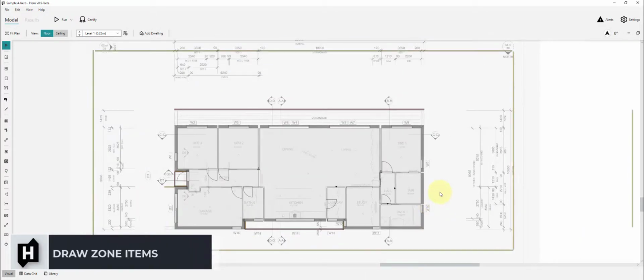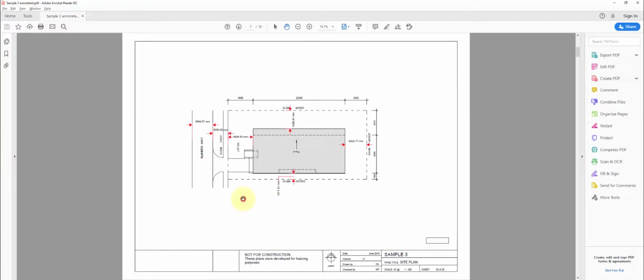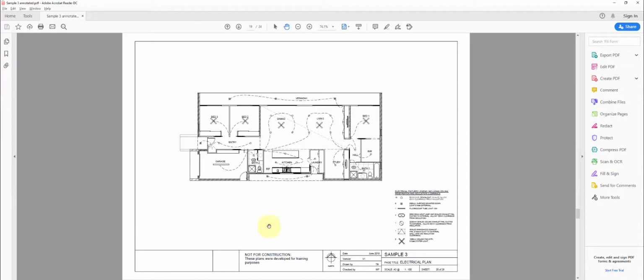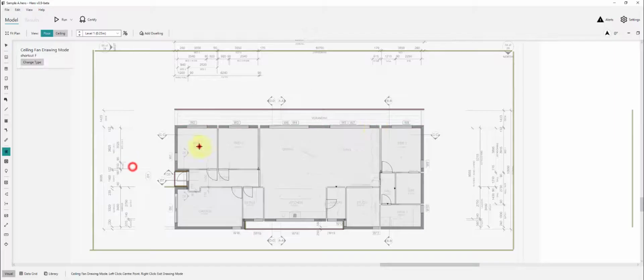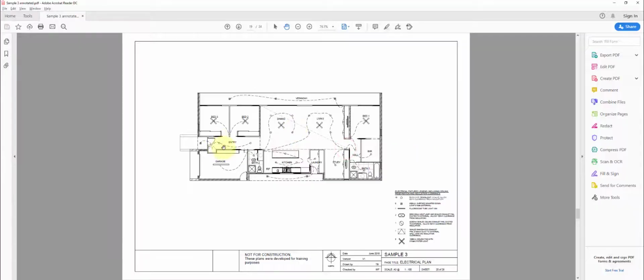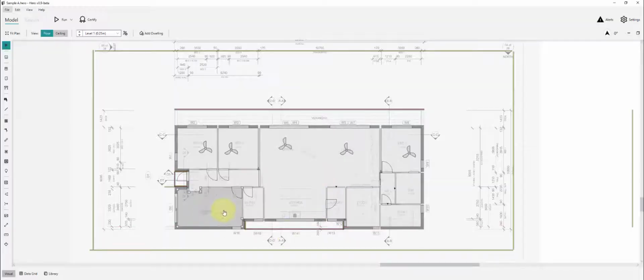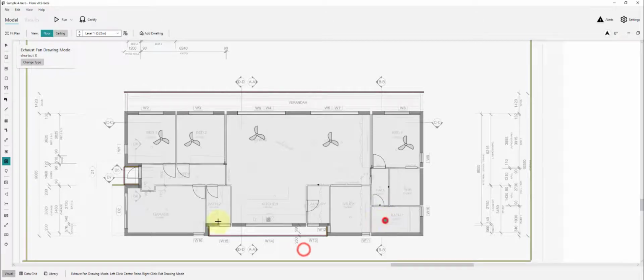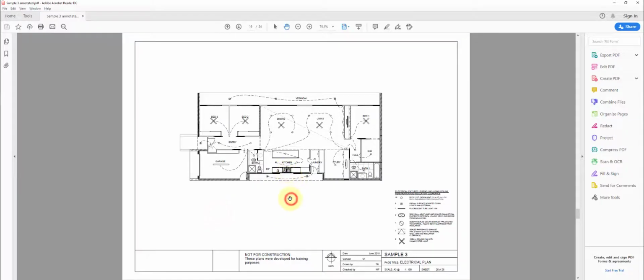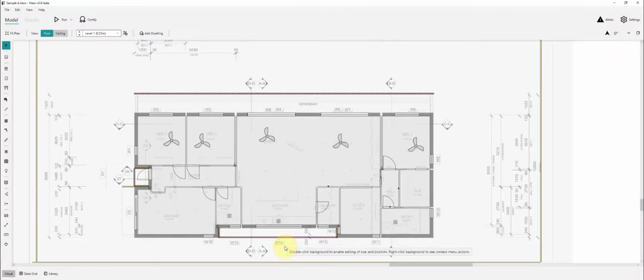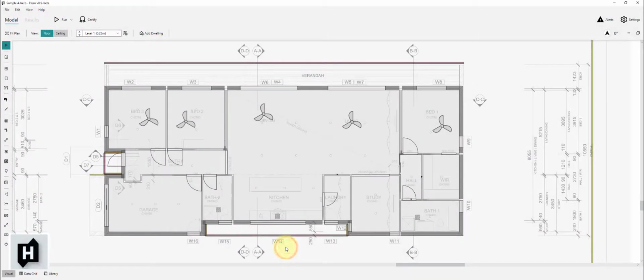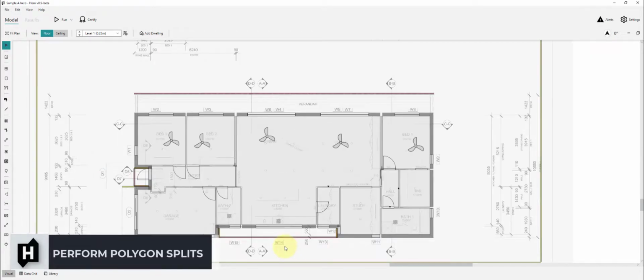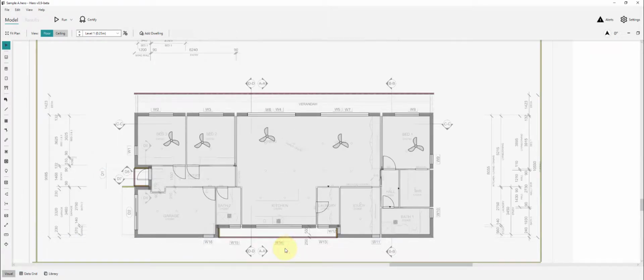Next we generally do penetrations, so let's flick to the electrical plan. Ceiling fans across here. In terms of downlights, we might do this as an example within the data grid, just using the numbers column, as all of the zones have downlight within them. So we'll leave that there. We'll just make sure we've got the exhaust fan in these two baths, and given that that was the first zone created, it's the kitchen, it's already been populated with an exhaust fan, which is that range hood. So that's penetrations done.